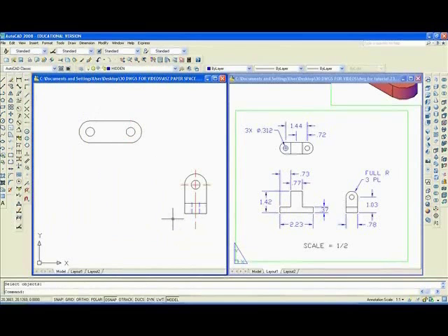And I can use a fillet radius 0 to do that and that, and erase. Try it again, erase. That area. That's all I really need for the solid, except that I should erase or get rid of these center lines because I don't need them. They'll only clutter the drawing.